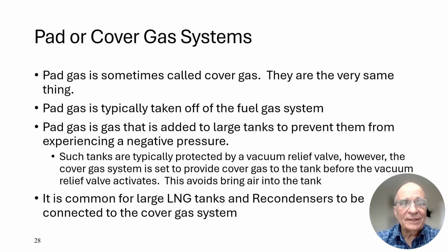Pad or cover gas systems. Pad gas is sometimes called cover gas. They are the very same thing. Pad gas is typically taken off the fuel gas system. Pad gas is a gas that is added to large tanks to prevent them from experiencing a negative pressure.